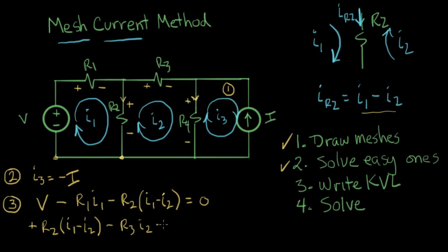So this is going to be a voltage drop, gets a minus sign, and it's going to be R4 times, this time it's I2 going down, I2 minus I3. And did we get home? Now we're all the way home. So our KVL equation is all that equal to 0.